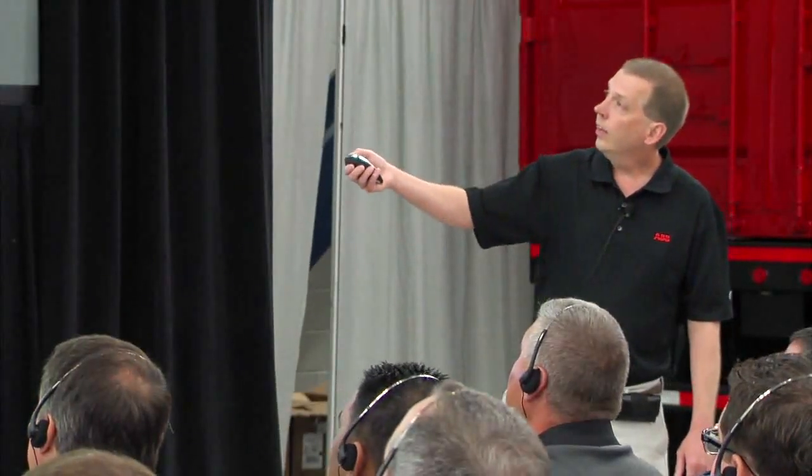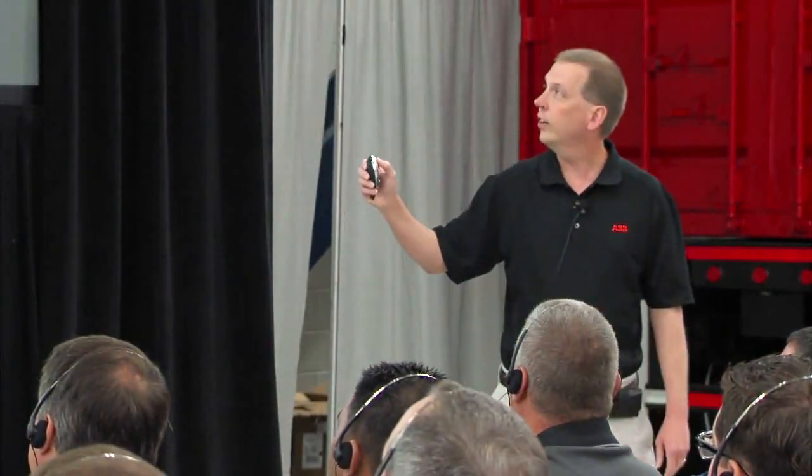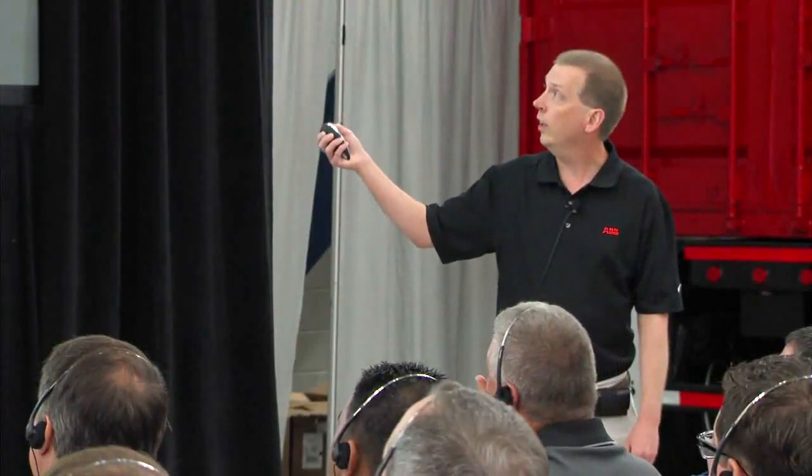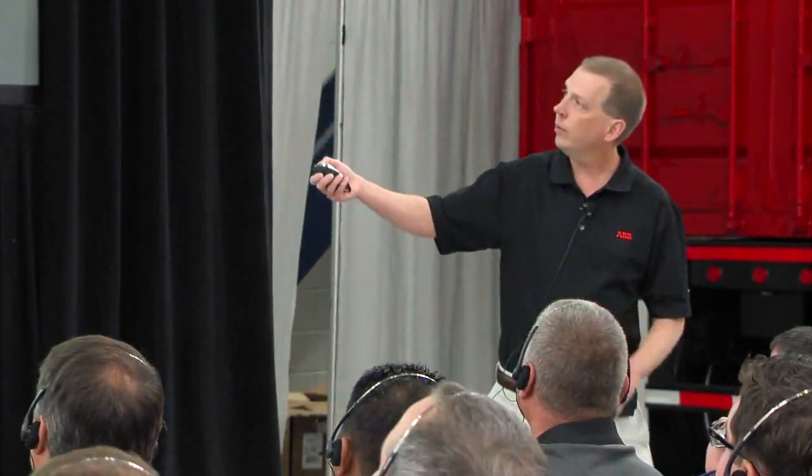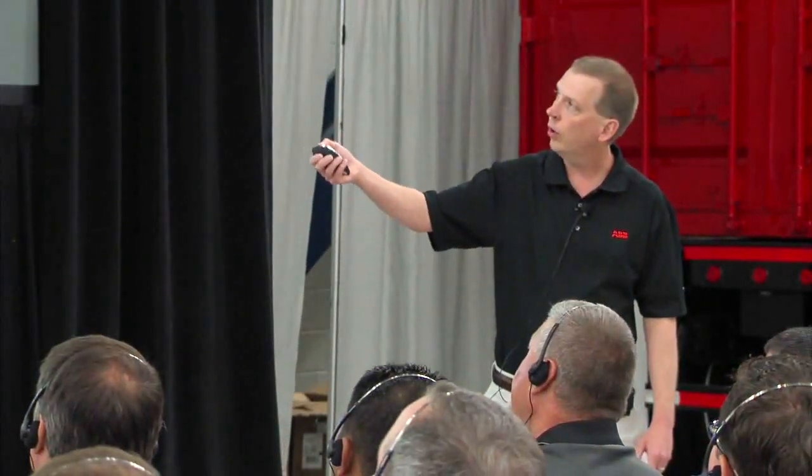And then some very clever engineers decided that they could do it without the encoder. They put in current sensors that all they do is measure the current going out to the motor. And they maintain in the drive what's called a model of the motor. Usually for this type of control, there's a tuning algorithm that happens when you first connect the drive to the motor.